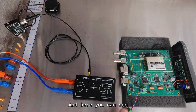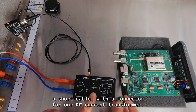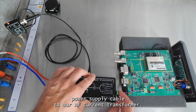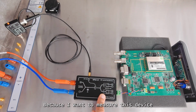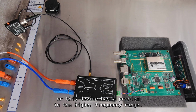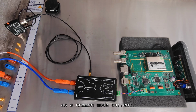And here you can see for the power supply of this electronic device, I prepared a short cable with a connector for our RF current transformer. Here we have the possibility to connect this power supply cable to our RF current transformer. I used the common mode connection for RF common modes, because this device has a problem in the higher frequency range. And for radiated emission, most of the RF currents are coupling into the cables as a common mode current.